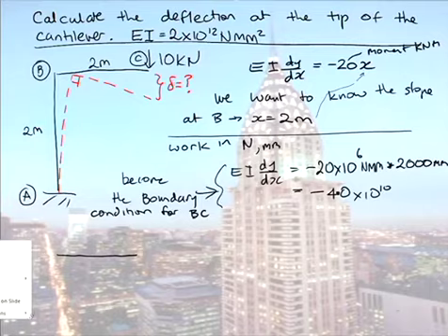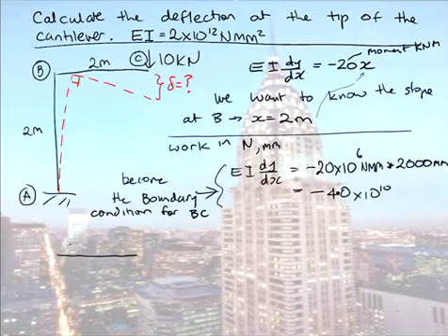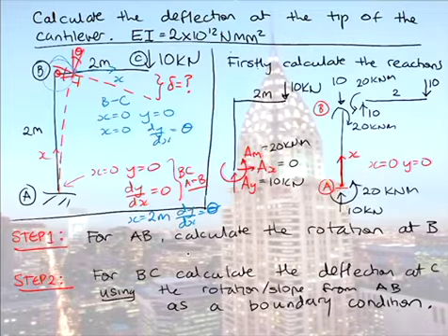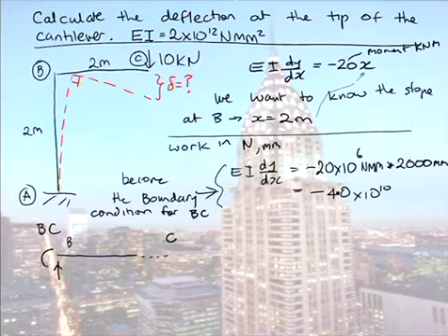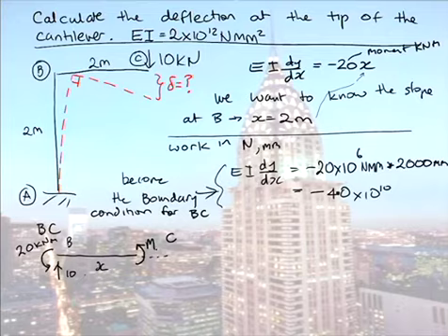So now we can look at the BC beam. Looking back, when we look at BC, we know the moment here is 20 in the corner and the shear force up is 10. This corner here is B, and I'm cutting just before C. So here I effectively have a known shear force of 10 kilonewtons and a known moment of 20. I'm making my cut at x metres, and I draw my unknown internal moment because that's what I'm after.